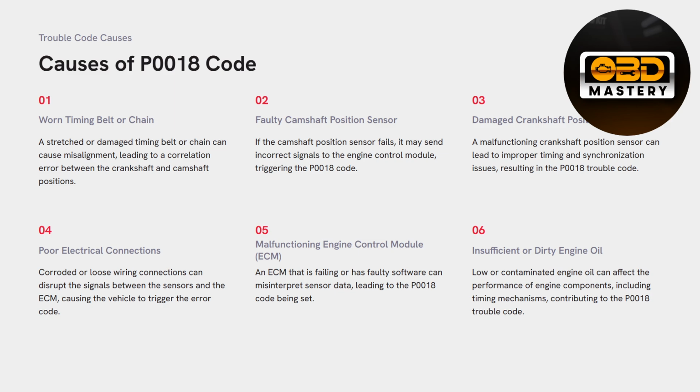And number six might be one of the biggest culprits ever: insufficient or dirty oil. Now, understand the viscosity of your oil. If your oil is contaminated with water, it's best to flush that. Usually you will have a kind of milky type oil, so if you have that, it's best to change the oil, do a whole flush, and get that done.